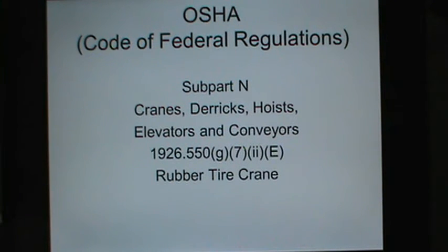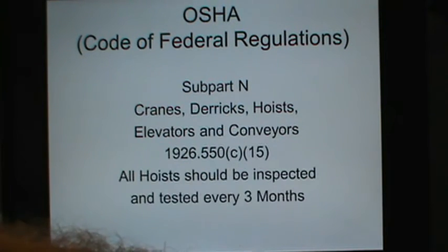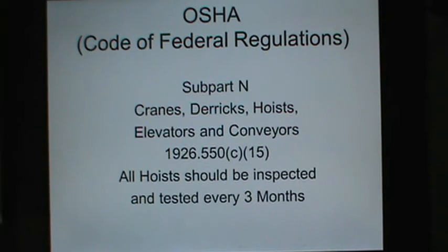The only other thing that I have in this book, and I don't even know, yeah I do, it's on here. If you flip a page, see if you could find 550C15. In the middle of that paragraph, we're told that all hoists should be inspected and tested every 3 months. So there you go. That is a lot. Subpart N is all about cranes, derricks, hoists, elevators, and conveyors.